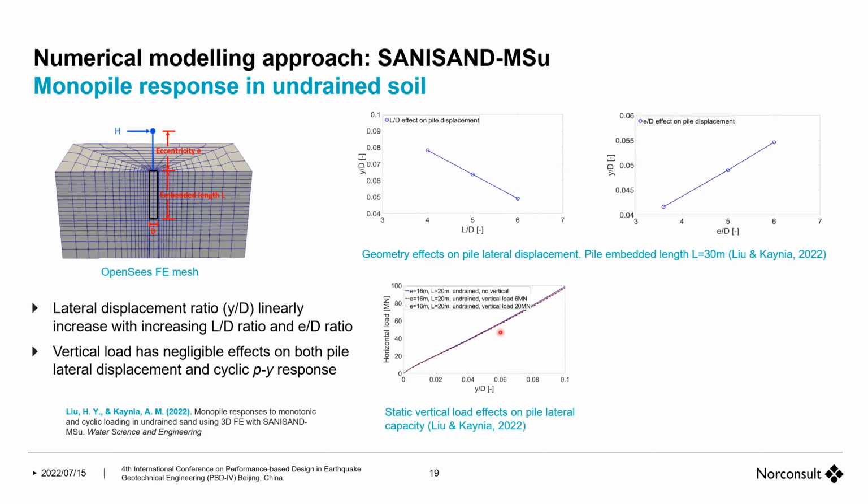Perhaps interesting is the PY. This result I like myself. In offshore wind, at least with the level of vertical load involved, this shows the effect of a vertical load. It shows that if there is no vertical load versus these 2 curves with vertical load, basically the displacement at the surface is not affected whether there is a vertical load or not.